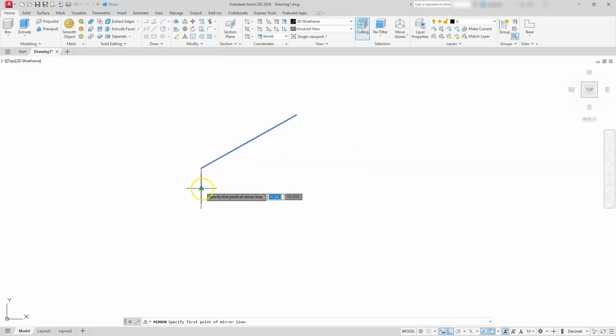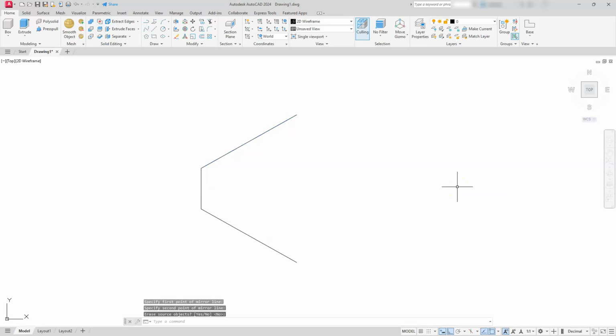I'm just going to select this midpoint. And if you don't have midpoint turned on, make sure you select the fly-out next to it and put a check next to midpoint. So I'm going to select this midpoint by left clicking on it. As long as I drag this direction, and remember I have my ortho on, so that makes things a lot easier. So I'm just going to left click here. Go ahead and hit enter.